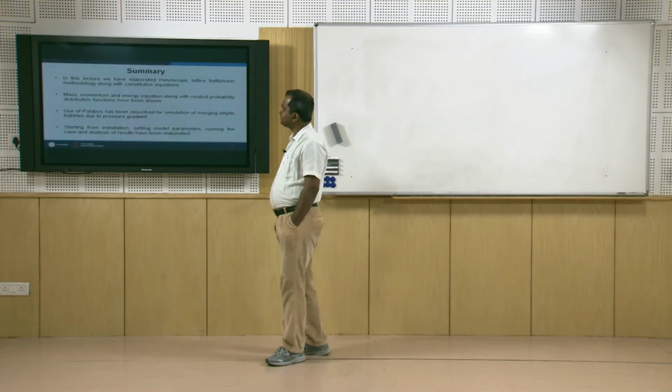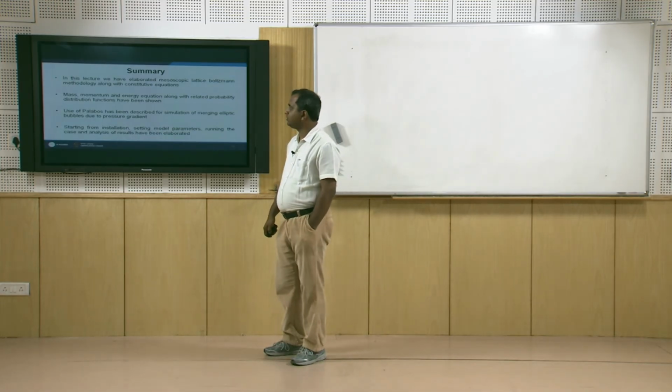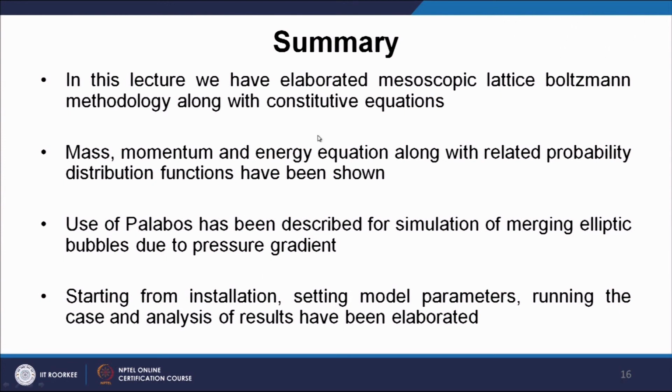Okay. So, let us summarize this lecture. In this lecture we have elaborated the mesoscopic lattice Boltzmann methodology along with the constitutive equations, and we have described the mass, momentum and energy equations related to the probability density function. We have also shown you one freeware called Palabos, and its use for the lattice Boltzmann equation: from installation, setting the model parameters, how to run, and how to analyze the results.